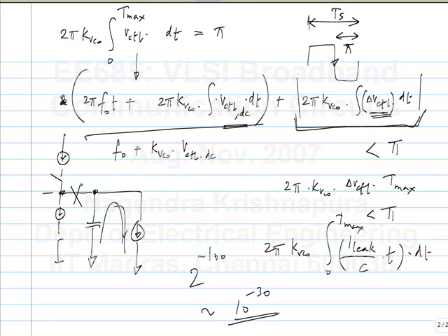You can just make this robust enough. I have not actually said how much the drift will be, but in practice it's not so difficult to make it not drift for, let's say, 100 digits or so. Some of these things also depend on the absolute value of the frequency. When you are operating at 10 gigabits per second, each bit is 100 picoseconds. So 100 bits is only 10 nanoseconds, which is not that long a time. So there, leakage is not a big issue.